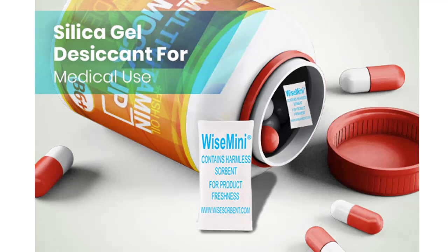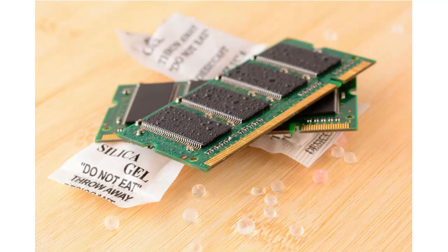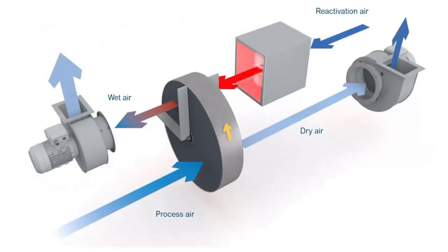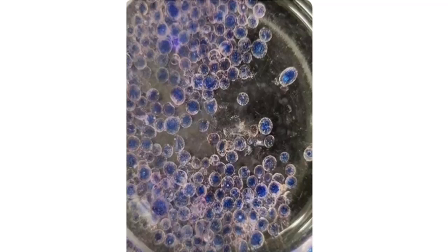When silica gel becomes saturated with moisture, it can be regenerated by heating it to 120 degrees Celsius for 1 to 2 hours, which releases the moisture and restores its drying capacity. This process allows for multiple uses of silica gel with minimal loss in efficiency. However, certain types of silica gels may pop when exposed to sufficient water due to the breakage of the silica spheres.